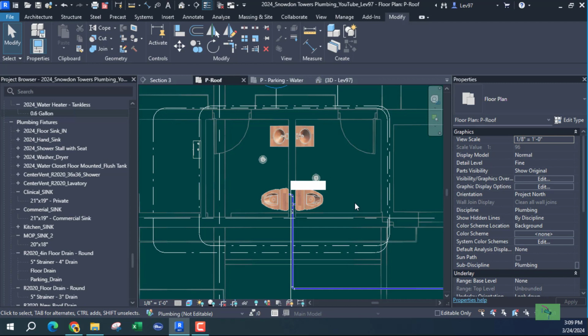You know, I mean, it's fun to change the colors of the pipe, change the size of the pipe, and get the GPM, the flow, and the fixture units and all that kind of stuff. But most of your work is going to be editing, and it's going to be, now, how do I get this pipe from point A to point B, or in other words, routing, okay, and how to maneuver in the architecture space.